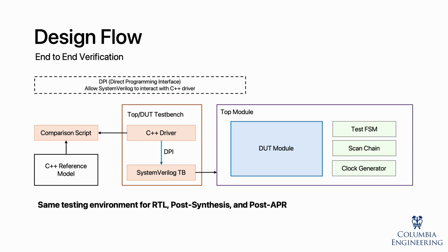The second part is the SystemVerilog test bench, which manages the timing of the scan chain and UART sequences. The two parts are connected through SystemVerilog DPI with exported functions. This end-to-end test bench has been deployed in all our verification flow, from RTL to post-synthesis and post-APR.